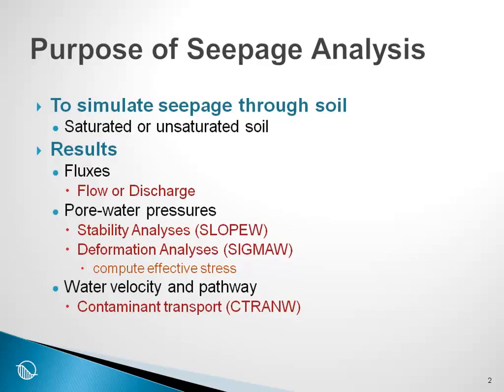Sometimes we may have excess pore pressures as a result of external loading due to the building of an embankment, for example, and then we need to know the pore pressures in SIGMA/W in order to compute volume change and consolidation, and we also need to know the effective stress in the ground because we know it is effective stresses that control volume change and shear strength.